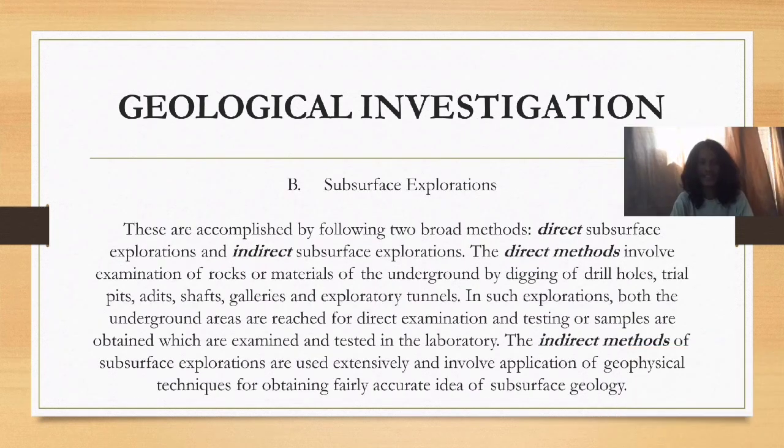Geological investigation. B. Subsurface exploration. These are accomplished by two broad methods: direct subsurface exploration and indirect subsurface exploration. A direct method involves examination of rock or materials of the underground by digging or drill holes, test pits, adits, shafts, galleries, and exploratory tunnels.